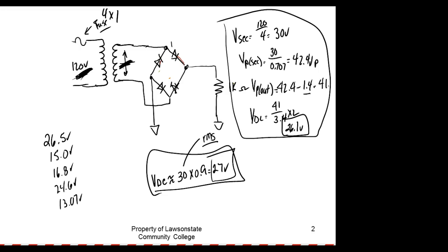But if I don't know that, if I'm just measuring to see what's there, and I measure 13 volts, and I don't know it's supposed to be 26, 27 volts, then I say, well, power supply is good, right? You understand? Because all you're looking for is getting something out of it, and you're not seeing what the voltage is supposed to do. Now this is the math that we use for unfiltered power supplies. As soon as I add that filter, this math is gone.